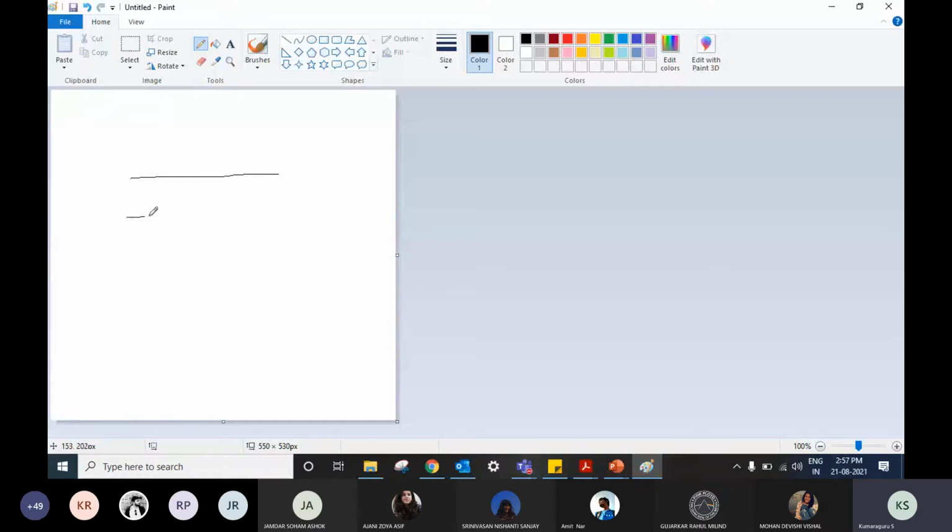So take, for example, any cross section of a slab, okay? Now any slab is going to bend, and it's going to bend down. The tension is going to be somewhere here, right? So in order to carry the tension forces, the concrete is very weak in tension. It is assumed to be cracked. So only the rebars will be carrying the main tension, right?